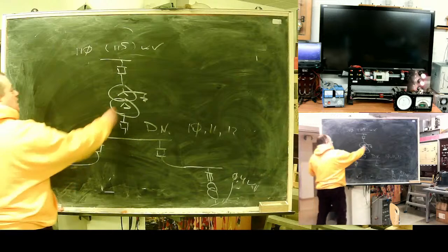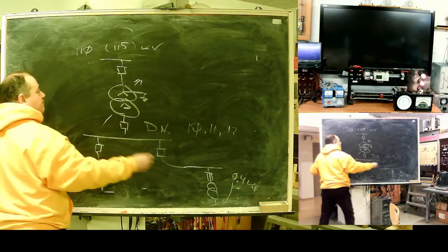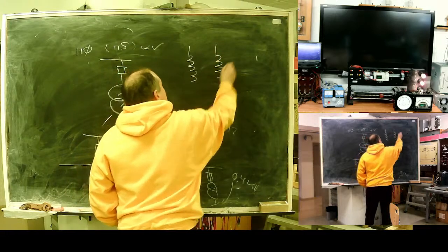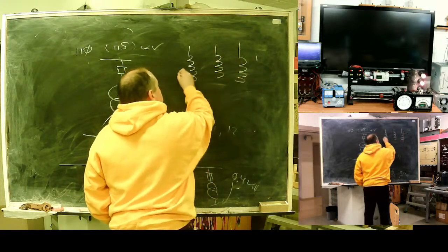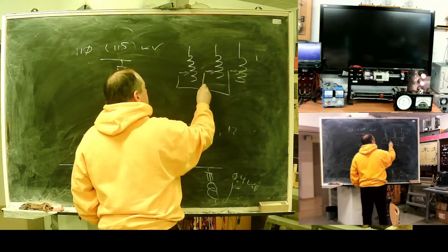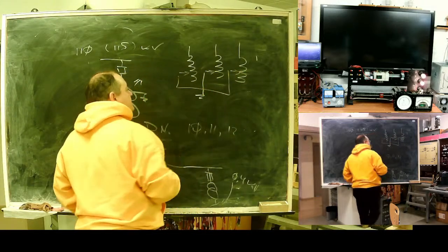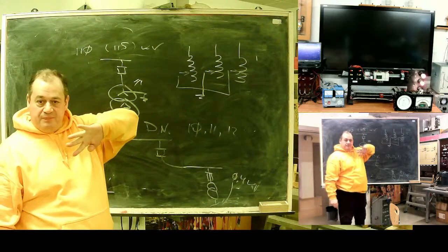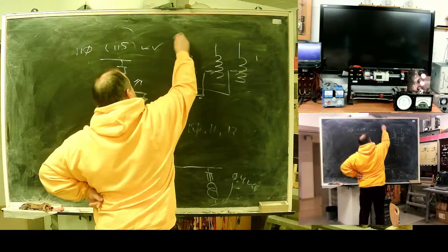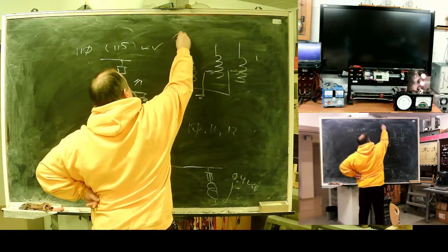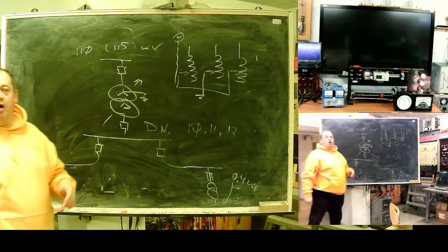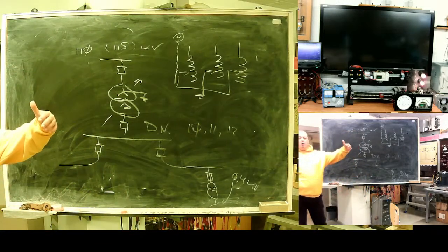How is it done? This transformer actually has a set of taps at the neutral side, and these taps can be switched. The transformers are equipped with a so-called tap changer. Older ones had a barrel-like one on the top.